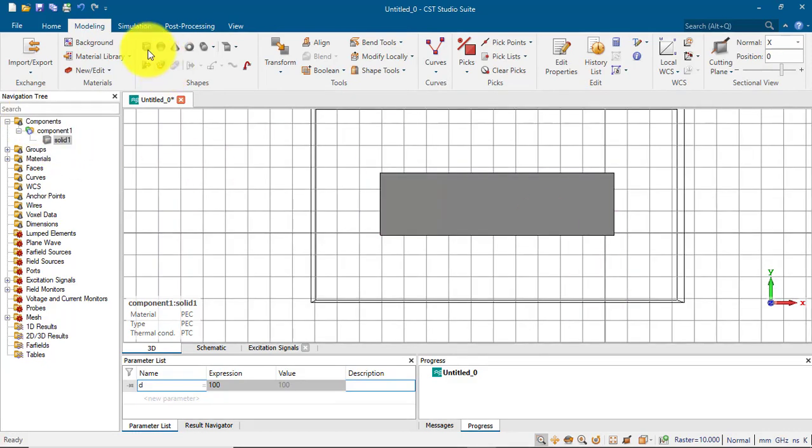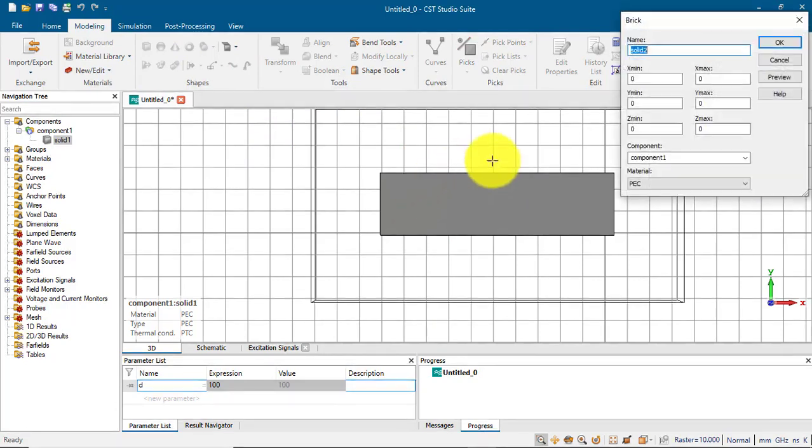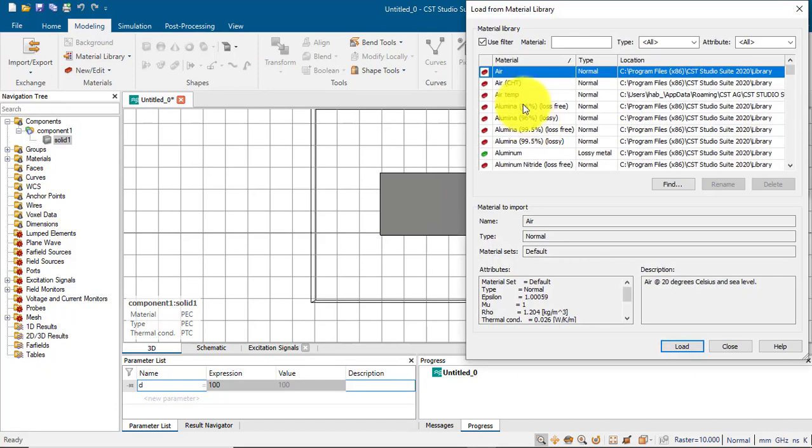Another way, we can press this, press ask to show dialog box. I didn't create it, okay? Press ask, you have, yes, see, I can put it as name. I can put any name here and put maybe dimensions like minus WW, minus LL, from 0 to T as a thickness, and change the material, load from material.